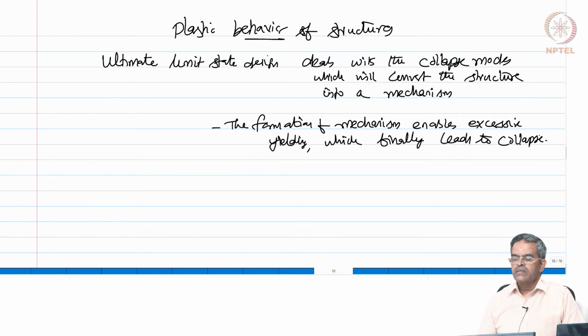We all know, friends, that steel is a very common construction material which has got enough ductility. Looking at the stress strain curve of steel, it is evident that the material has got good capacity beyond the first yield. Therefore, any design procedure which limits the strength till the first yield, like an elastic design, is not a good design procedure. So, the material strength beyond yield, which is having enough reserve value, is not utilized.